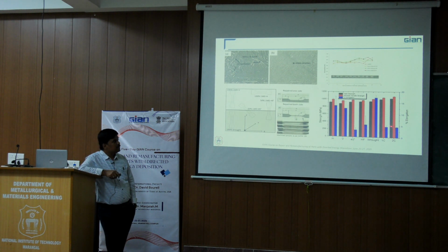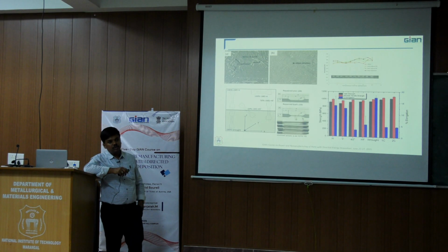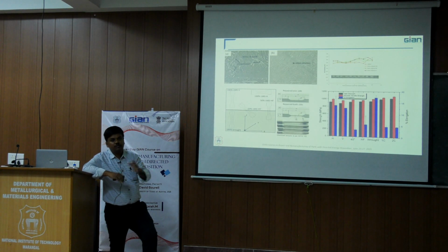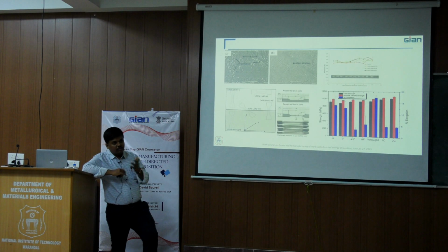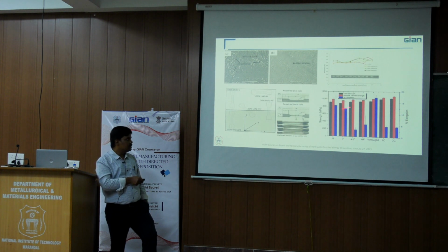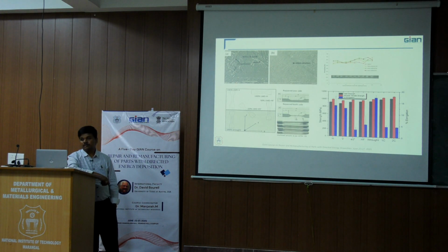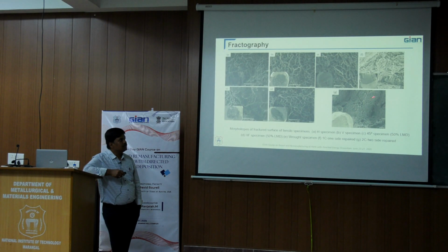And we have compared all the mechanical properties with respect to strength, hardness, as well as elongation, and even the fatigue properties we have tested. Because ultimately, once you understand all this data, only then can you use it for repairing applications. Otherwise you end up with different mechanical properties, and even if it is repaired, it may not be useful for the application. If you see, the yield strength as well as the ultimate tensile strength is matching with the rod materials.